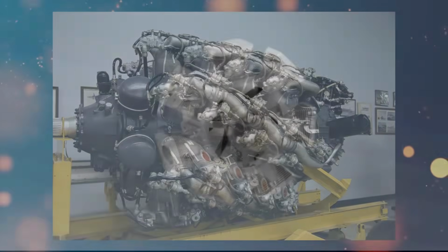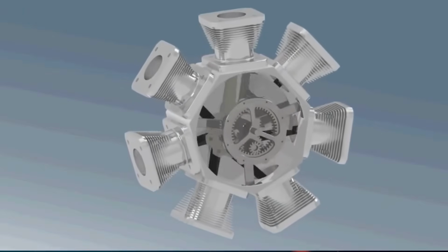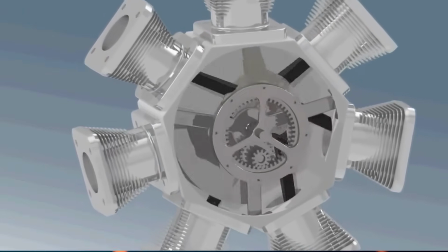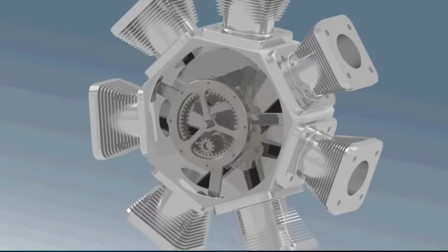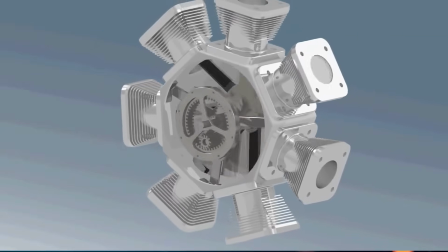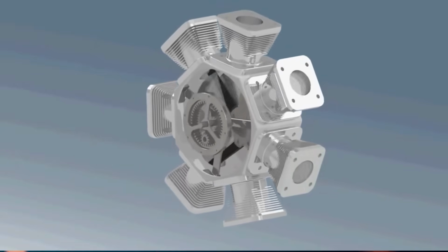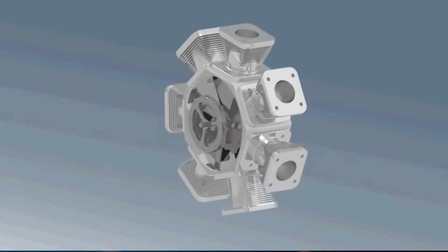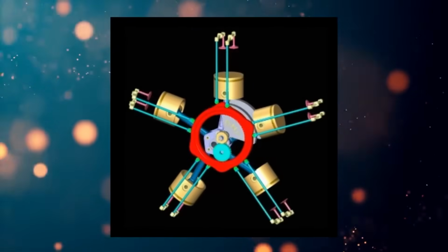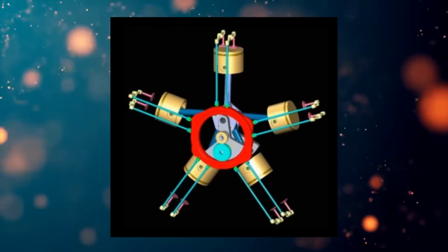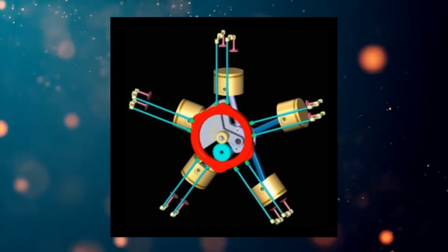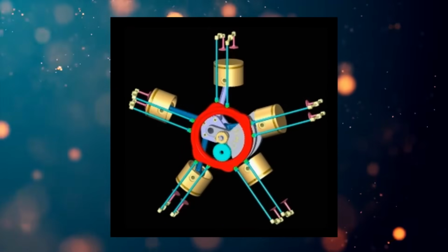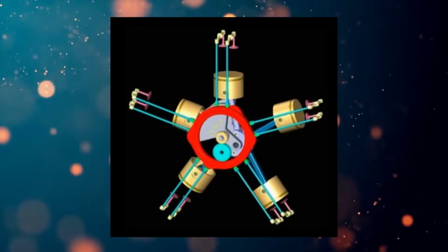To achieve the required power characteristics, a radial engine may consist of more than one star-shaped section. Usually, four-stroke radial engines have an odd number of cylinders in one section. This is due to the optimal firing order in the cylinders. An odd number allows the spark to be delivered to every other cylinder. In a 5-cylinder star engine, the firing order is 1, 3, 5, 2, 4. Then we return to the start of the cycle with the first cylinder.